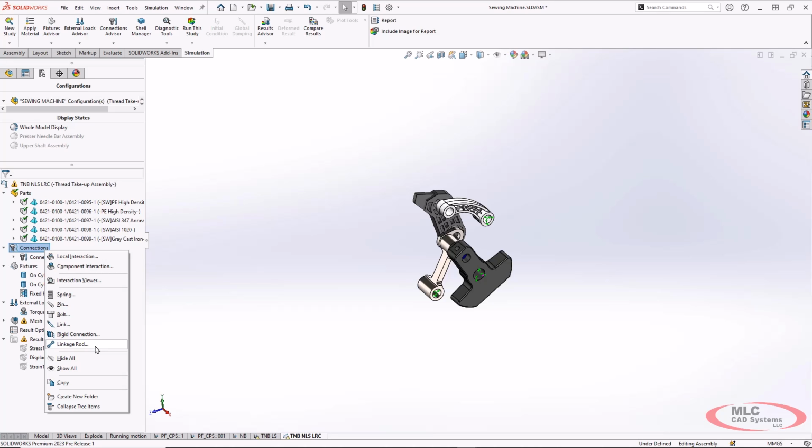of your typical rods, but it's all virtual, so you don't have to mesh it, but you still get the effects in your assembly. It's the same reason you would use virtual bolts, which are very commonly used, but in certain circumstances this can be good. But now in the new version, it's allowing us to use this in nonlinear studies. Just because it is in nonlinear studies, you do need your Simulation Premium license in order to use it, but it's a great new feature to save time.